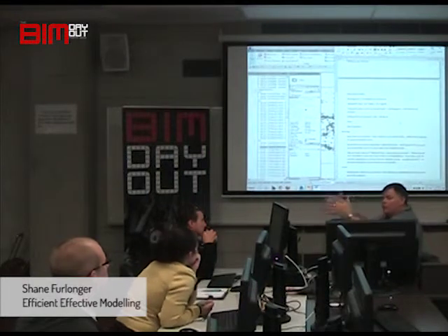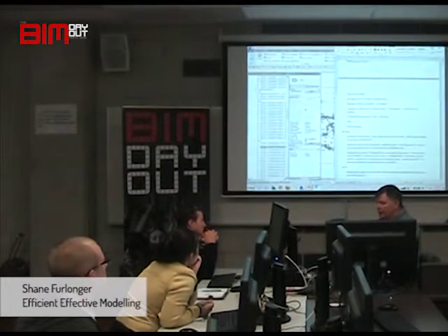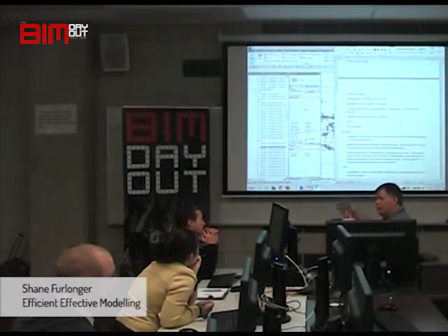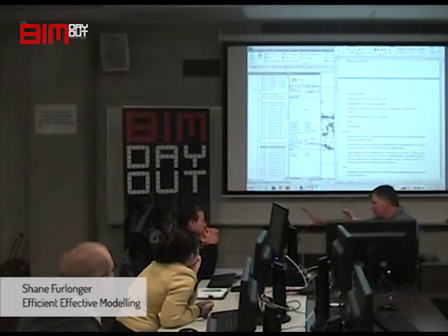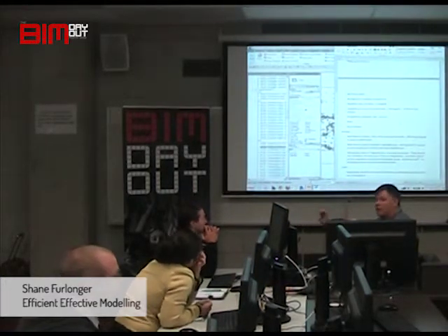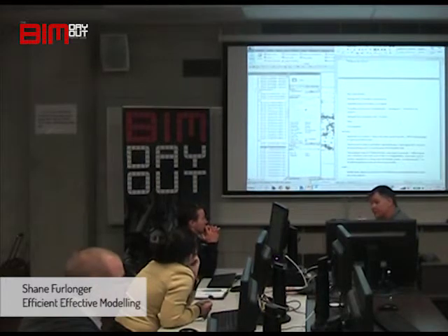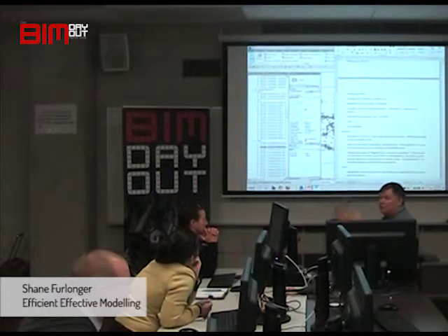If you're going to do it window by window, your elevations of each one in the model, you may have them in the wall and they may be spaced differently. So if you just put them in one elevation, you're going to have funny looking spaces between them as you put it on the sheet. So the only way to change that is to do an elevation for that window, an elevation for that window, and you put them on each of those elevations on the sheet, and then you can move the views down so that you get the views lined up how you want them to look. Those really nice and all that.